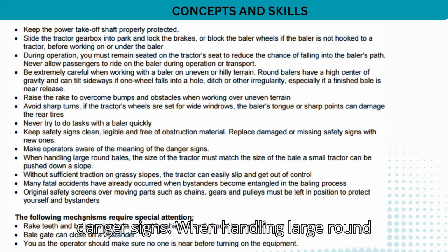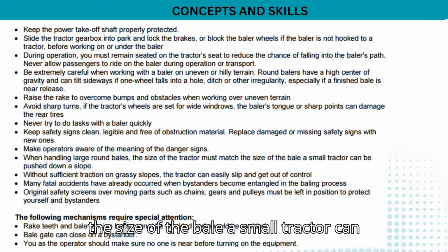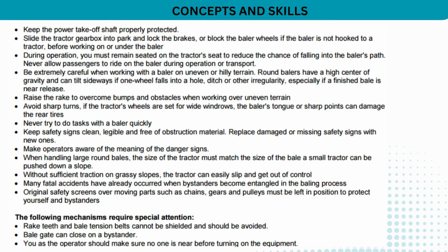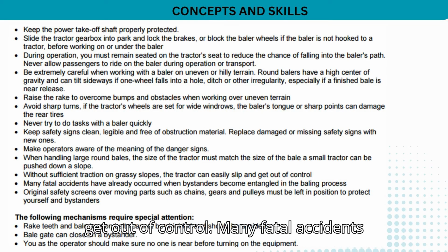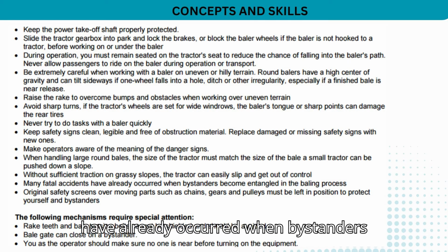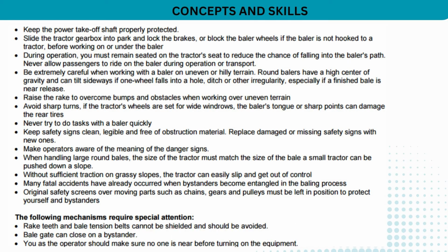When handling large round bales, the size of the tractor must match the size of the bale. A small tractor can be pushed down a slope. Without sufficient traction on grassy slopes, the tractor can easily slip and get out of control. Many fatal accidents have already occurred when bystanders become entangled in the baling process.